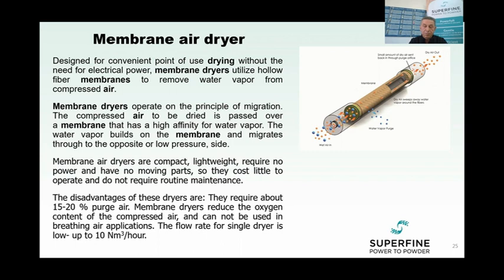On the other hand, don't skimp on drying and specify dew points that are too high. Damage from water in the system is equally expensive. Users should only supply the degree of dryness needed for each application, especially when it varies by process or machine. And like any system, consider upfront and operating cost, flow rate, and performance capability when specifying a dryer.